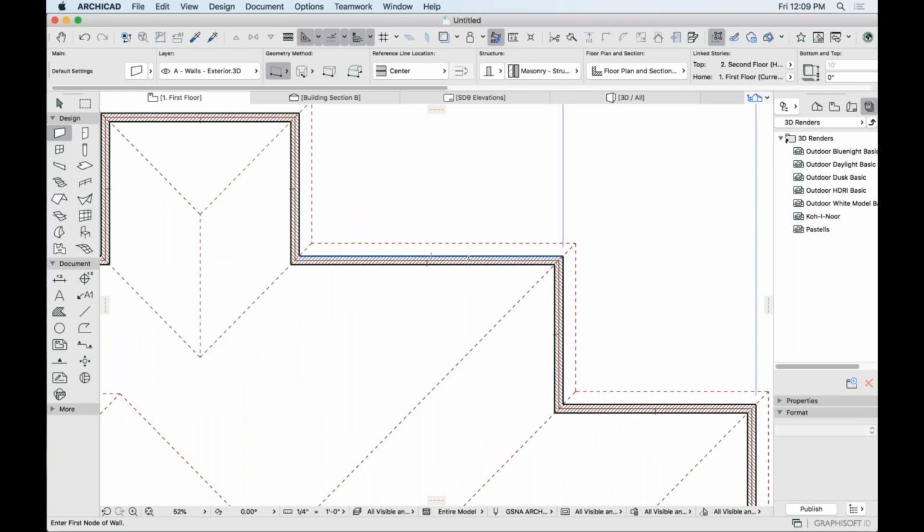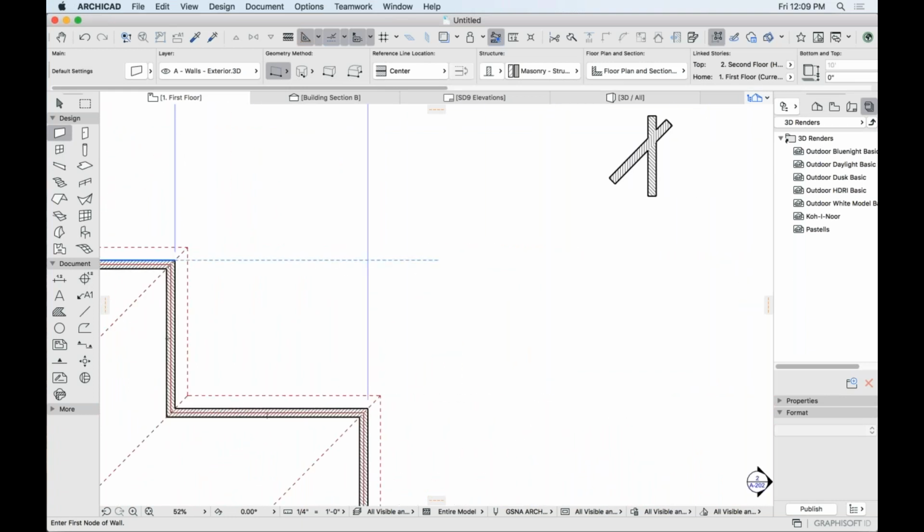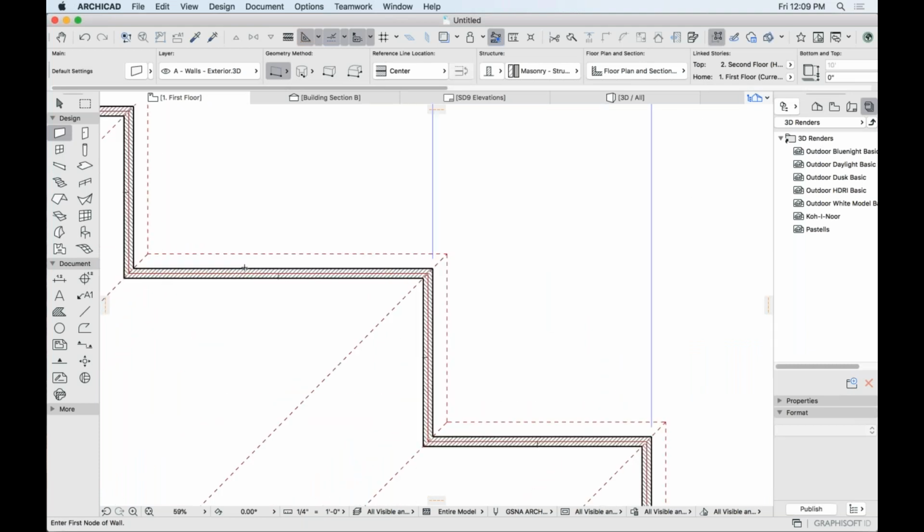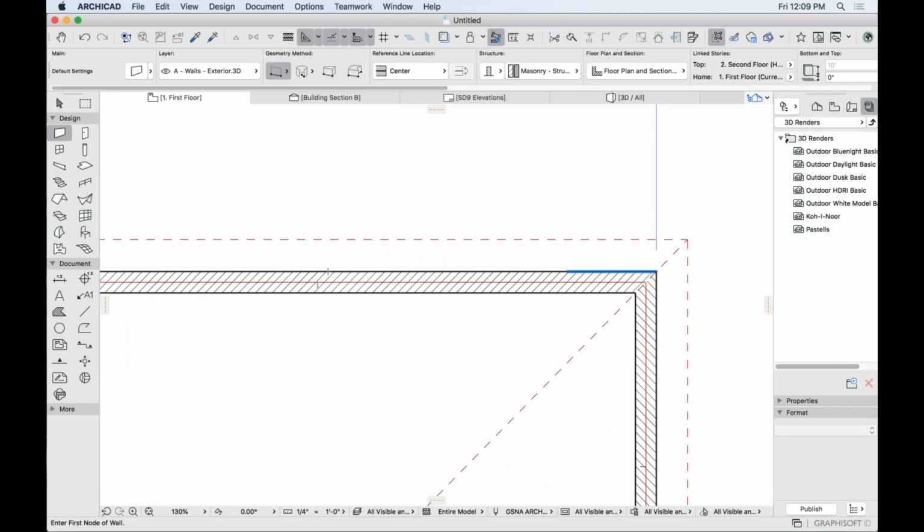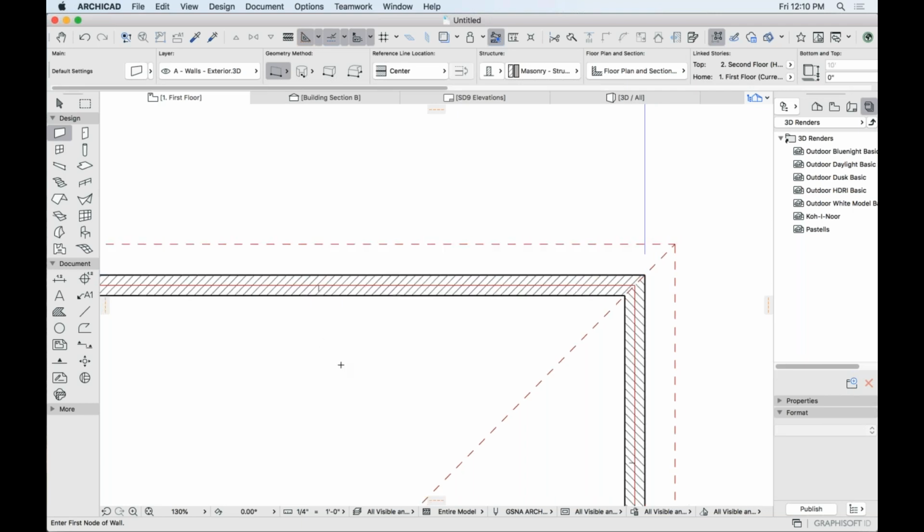See that lightsaber effect? Now, if I drag my cursor off to the side, it acts just like a tape measure and it extends from this wall. So if I needed to draw another element that aligns perfectly with that face of that wall over there, I can do that. So I can hover over faces of elements for just about a second until I see the blue highlight appear. If I want that blue highlight to disappear, I can either hit escape or I just move my cursor and then move it right back over it and it disappears.